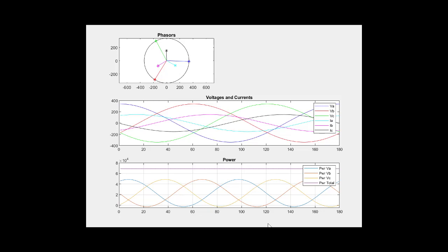That's why 3-phase electrical systems, or power, is so important to us. If you ever see a cross-country transmission line now, you'll look at it and go, yeah, there are 3 lines on that. There are nearly always 3 lines. Now, if you get into a city where you're servicing homes, they split a pair of those off, or one line. But across country, there are always 3 lines, and that's because they want a constant flow of power through that system. That is the whole point of 3-phase. It'll be used in lots of applications and is pretty important.